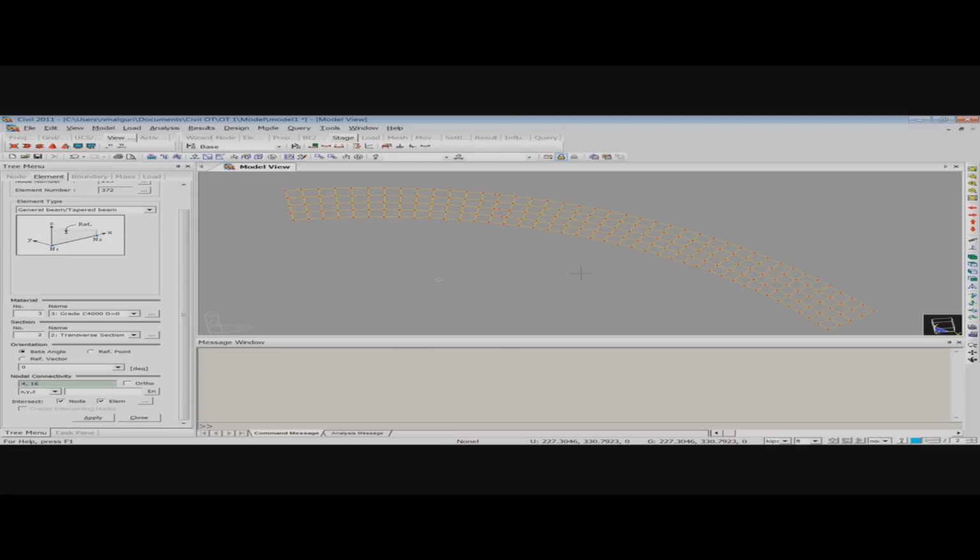The grillage model has the stiffness of the bridge in the longitudinal direction, which is represented by the composite sections, and the transverse stiffness of the bridge is taken care of by the transverse elements that have the section properties of the deck slab and the material properties of the slab, but with density as 0. So in this way we have modeled the superstructure.